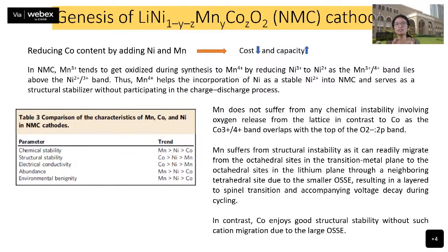Cobalt mines are located in very specific locations in the world. A technology which is going to be used by all and controlled by few is not a good situation. So if you want to use less and less cobalt, and use more nickel and manganese, which are a little bit more earth abundant, it is going to be better for the device technologies which are going to come. That is why there is right now an emphasis on NMC cathodes.